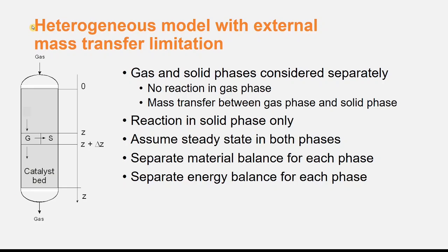Now we will look at a heterogeneous model for a packed bed reactor. In a heterogeneous model, the gas and solid phases are considered separately. Here we are considering gas and solid phases, but it is also possible that you have liquid and solid phases.